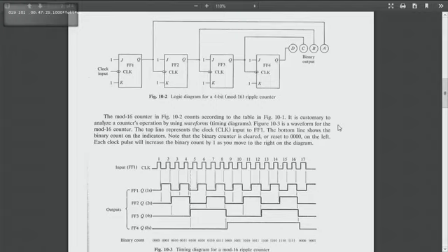For example, if you wanted a 10-second timer, like a light to go on after 10 seconds, and your clock frequency is, let's say, 1 hertz. You build a modulo 10 counter, whether synchronous or asynchronous, and I'll tell you a bit about that later. You feed your clock pulse at 1 hertz. The moment it reaches 10, the output should become 1, just like what we did in our last lectures. The only difference is now we are looking at asynchronous.